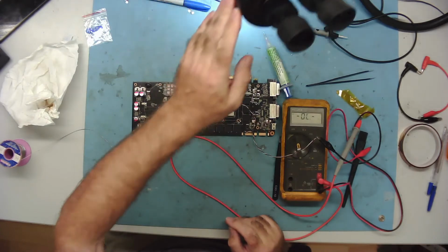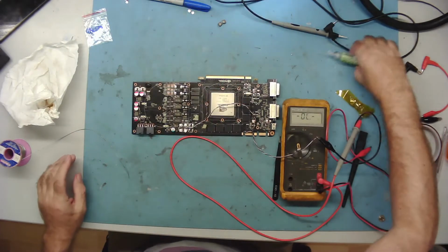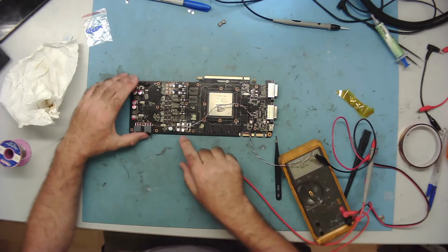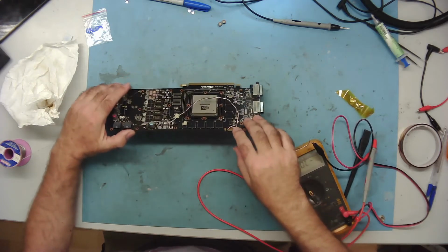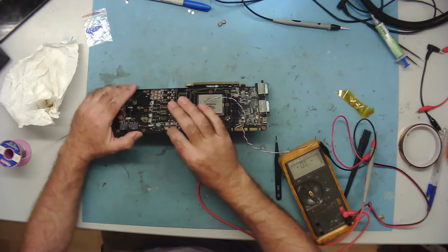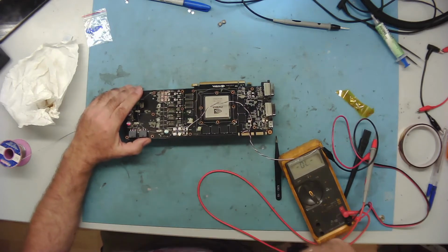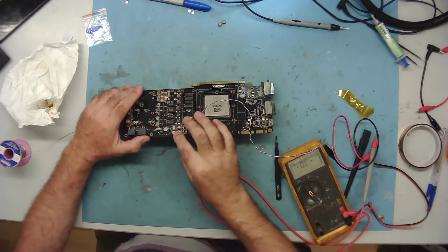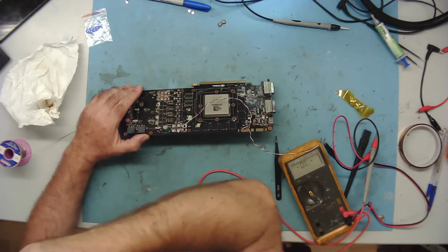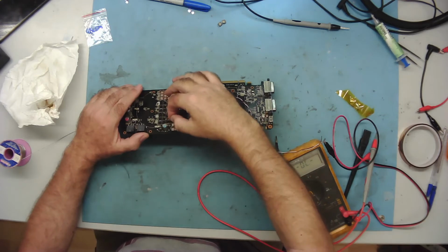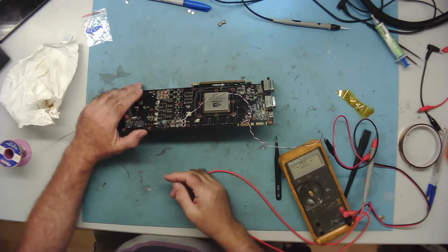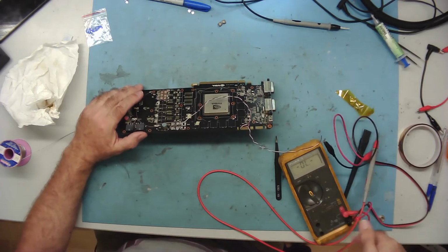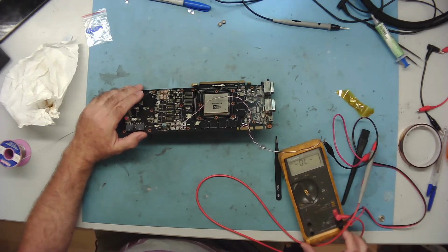Yeah, so what I've done is I've made a mess of the bench. I basically tagged this wire on here, and then I've wrapped it around here a few times, so I don't want to put any strain on that pad. It's quite easy when you're doing this sort of thing to actually rip a pad off the board, so you want to be careful. But we need to do this to see effectively where that goes. I found it too hard to hold the probe this side and get on the other side to see where it goes. So that wire is just clipped to the black lead of the test meter, into the negative.